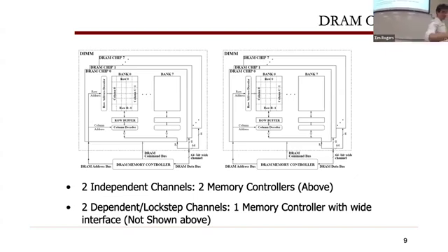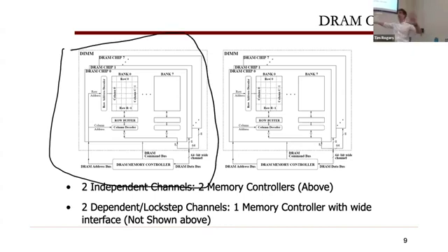So a channel basically means that there's 2 logically and physically independent memory systems. Whole other set of wires, whole other memory controller coming out of the chip that allows you to double the bandwidth, double the area, double the bandwidth. Right, like a government project, make double the cost and get it twice as slow.